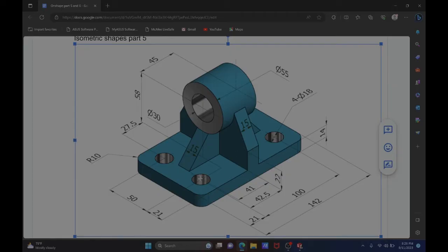One more thing that I want to do in this case, I want to place these circles right here. Notice I have four of them. Okay, this is symmetrical. They tell me that this is four. I have four circles whose diameter are going to be 18. Okay, the distance from the center of this circle to the edge is 21. Okay, by this, and then from the center to this edge is 21. Therefore, I'm gonna have all of those circles be the same.